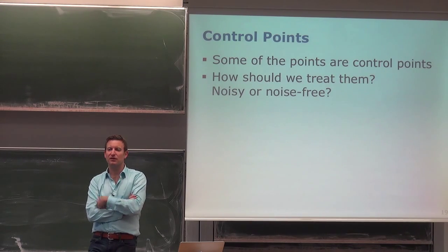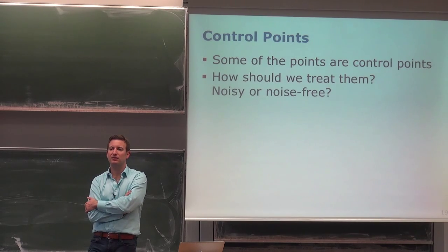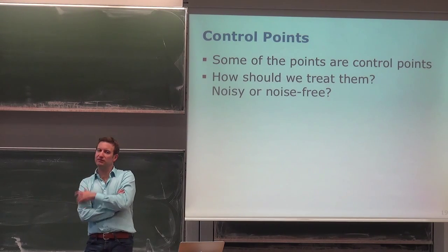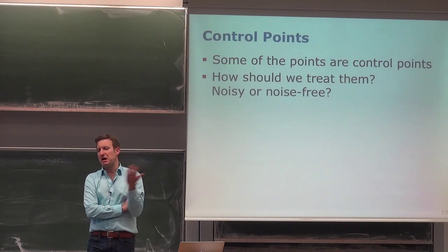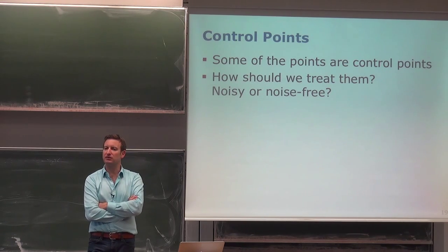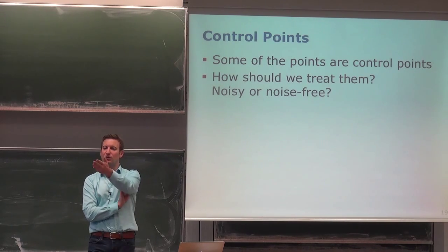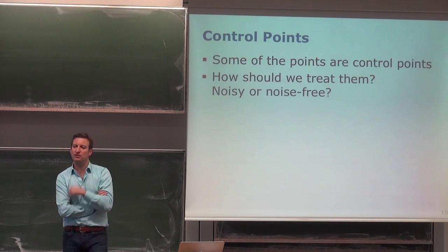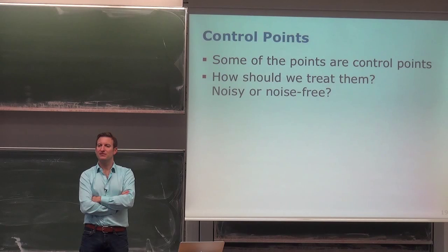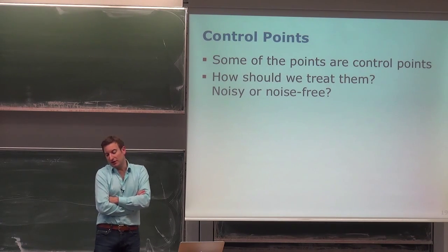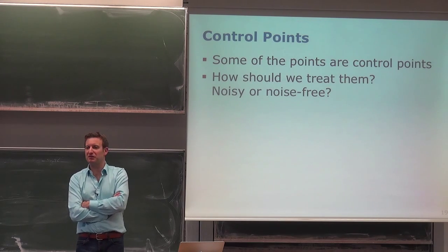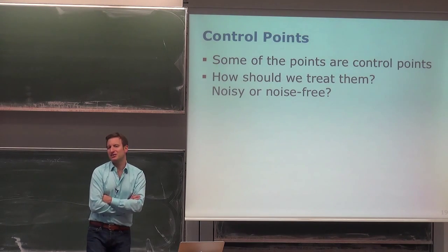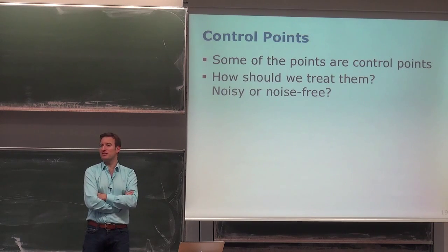There are more reasons. They should be much more accurate. Yeah, they're definitely more accurate, but even if I say they are 100 times more accurate, I could take that into account in my standard deviation, so that would not be a problem. So you're more on the side that we should treat them as noisy, although the noise is comparably small to the points that we are observing. But maybe because it's the only connection to our reference frame. It is the only connection to our reference frame, that's true, but if this connection is noisy, I could argue I should take this noise into account.